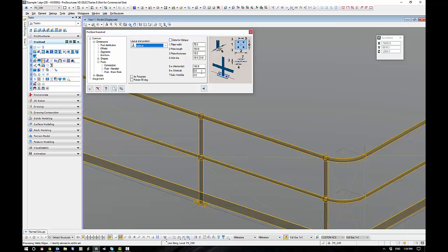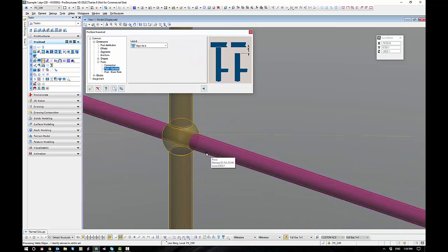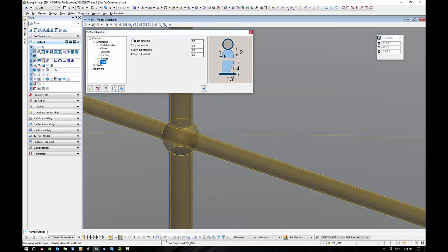Okay, now those are my settings for pretty much the standard flat web forge handrail, and don't forget you can use polyplate if you get some obscure size. This is worthy of note. You can notice I don't modify, I just keep these as is. I don't try and drill the balls, because that would be a Boolean operation, and the metadata makes your model really big, so please just let that interfere like it does now.